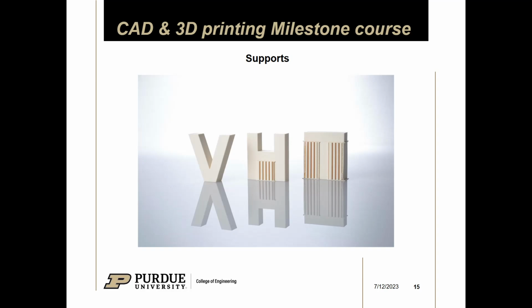But honestly, for the H, if the bridge isn't too long, you may not need these supports at all. But for the T, the only way to fix it is by changing the orientation of your prints. So that's something to keep in mind. If you think about which direction your 3D printer is going to print your part, you can avoid certain situations like this. This person wasn't really thinking, they printed them straight up. But again, depending on your needs for your part, you might purposely print in this orientation.